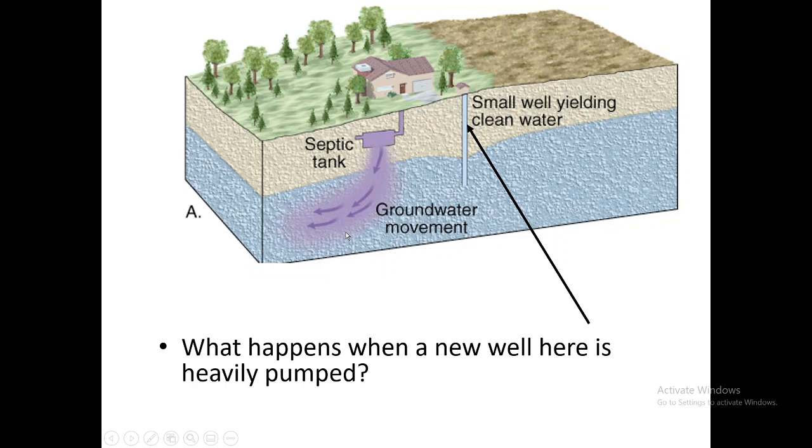So in that case, we will be also finding out different other water wells, and their characteristics regarding the quality of water. We can have a monitoring well here, we can have a monitoring well here, then we can observe their characteristics, their qualities, and then we will find out that in this well the water is getting contaminated, while in this well the water is not getting contaminated. So because of this difference, we can distinguish in which direction the contamination is likely to travel.